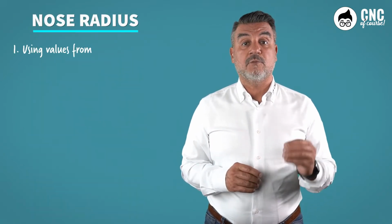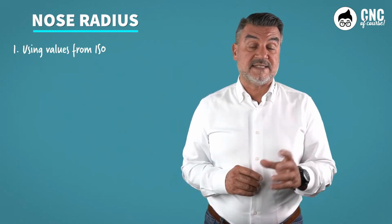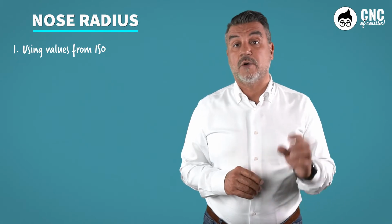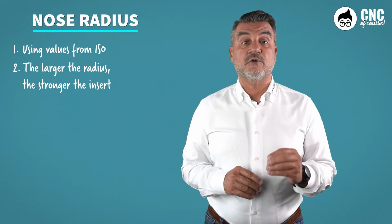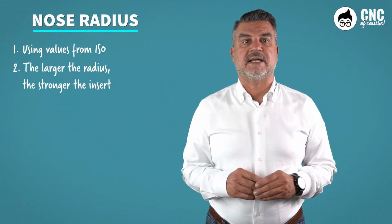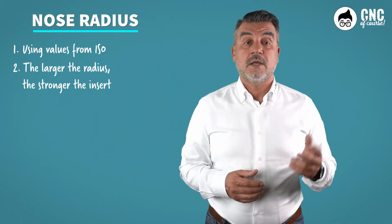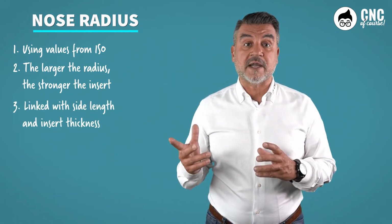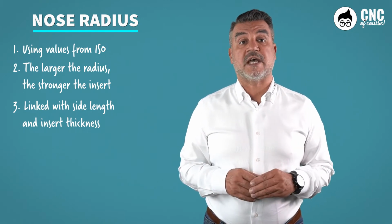Number 1. We will use one of the values given in ISO. So for example, among the most used, 0.8, 1.2, 1.6, 2.4. Number 2. The nose radius has a significant influence on the strength of the cutting edge, so a larger nose radius is used for heavy-duty cutting. Number 3. The nose radius is related to both the side length and the insert thickness, as well as to the cutting edge geometry.